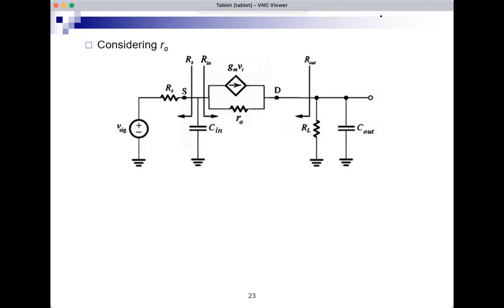In OCTC, if I want the resistance seen by Cin, so this is Cin, now I'll have a test source here, and I will have Rs. I set all the sources to 0, so Vsig becomes a short. That's Rs. And from the other side, I have the MOSFET, gmVi with RO and RL. And Cout is open circuited.